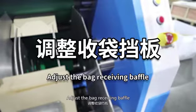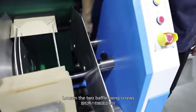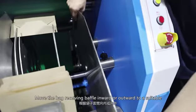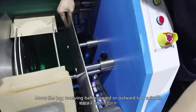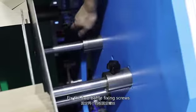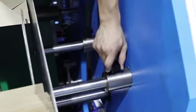Adjust the bag receiving baffle. Loosen the two baffle fixing screws. Move the bag receiving baffle inward or outward to a suitable position according to the width of the bag surface. Fix the two baffle fixing screws.